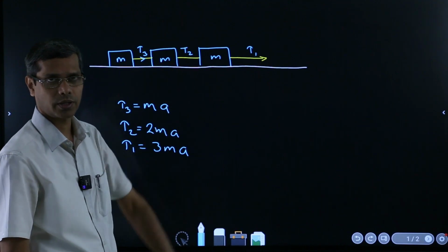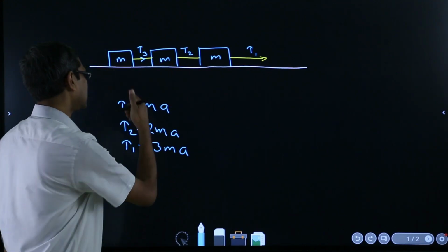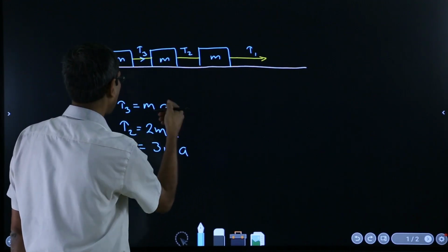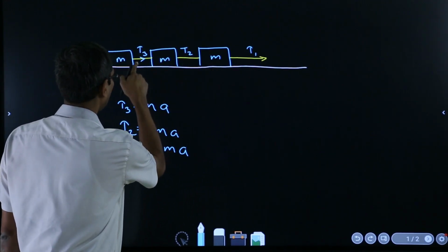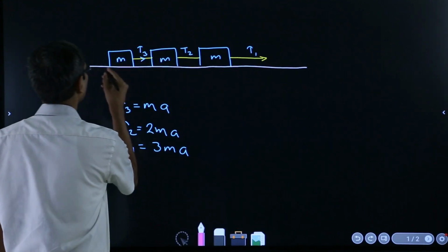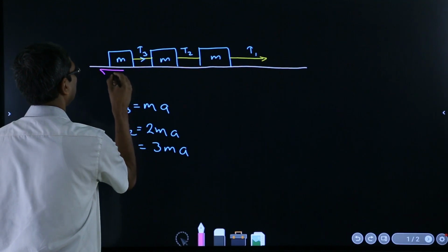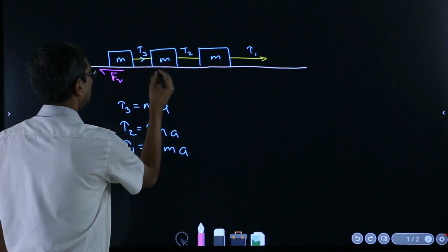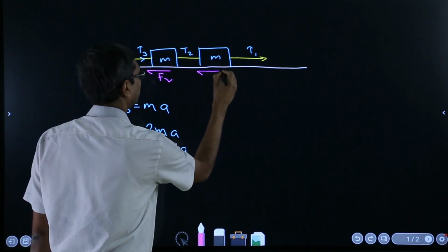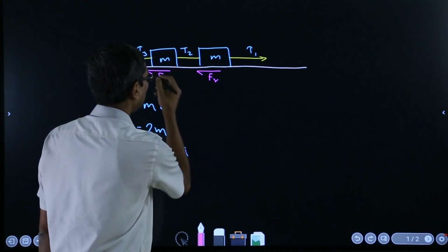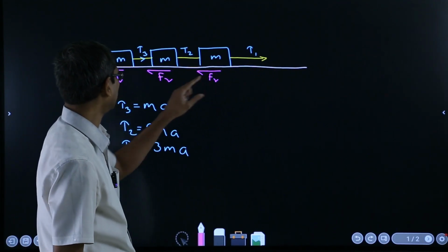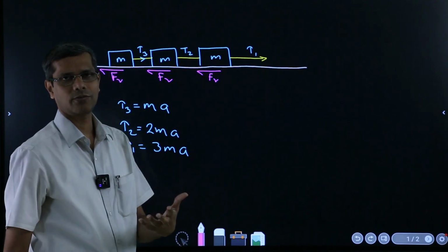And if friction exists, that friction also keeps on adding here. So this one is acting against only one friction here, okay. If here the frictional force is Fr, here again Fr, here again say Fr, then this tension is working against all 3 frictional forces.